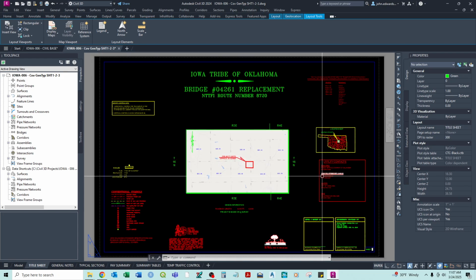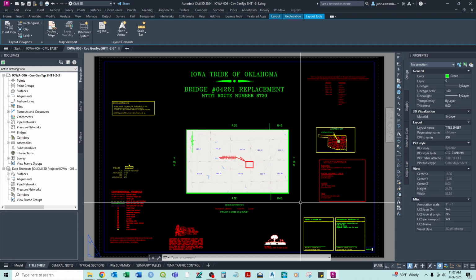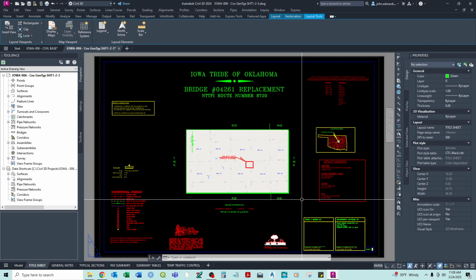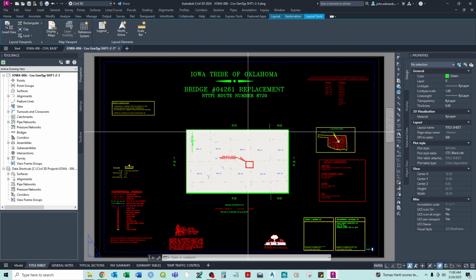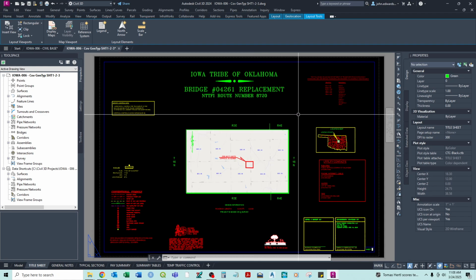So, and we also have multiple other sheets for different drawings, or different drawings that contain multiple different sheets throughout. And sometimes it can vary depending on what you need to be in your drawing. So some things like survey control or a watershed map, these will need to have their own drawing essentially in model space. That it's good to maybe XREF the design or at least the survey into there and then manipulate that from there. So that's why it's good to always have separate drawings for some of these. It just depends on what the base is.